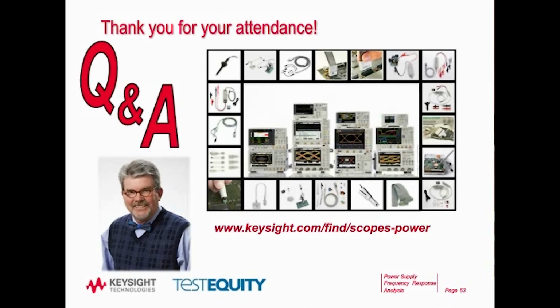And that's one advantage of the network analyzer, is that you can do this dynamic amplitude setting. So you can start at a higher amplitude where perhaps distortion is not occurring, and then as you move up in frequency, you ramp down to a lower amplitude. The scope can't do that, at least it can't do that today. So it is a little bit of a guessing thing as to what amplitude you can set as to when distortion will occur, and you can just do it trial and error with the scope. I would start low and begin increasing.